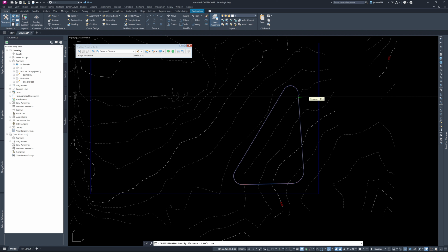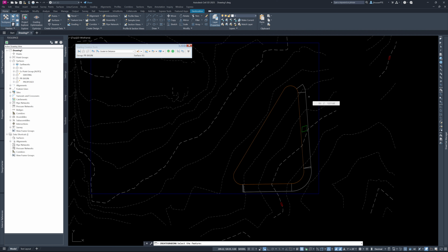Okay, now it's also going to say slope or grade. In this case, it's going to be a level base and berm, so we can do grade, that's fine, and we can say 0. All right, so what you see there is our grading object, the first steps of this whole process.